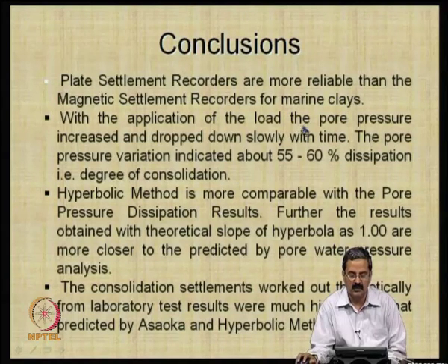With the application of the load, the pore pressure increased and dropped down slowly with time. The pore pressure variation indicated about 50 to 60% dissipation degree of consolidation.